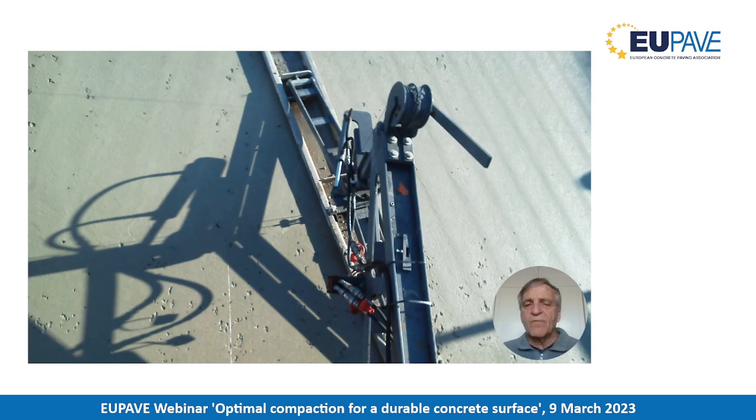When you don't have enough, this is about 90% of the issues, when we have these rock pockets on the surface of the pavement. The large probability of why they're there is exactly what we just talked about in the last slide, which is, is there enough paste to actually fill the void spaces that are part of the gradation system, or the volume of voids.